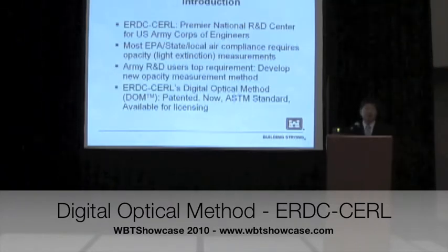EPA, as well as state agency, issued a permit to the air pollution sources or stack owners at installation. All the air permits require opacity measurements. Opacity means how opaque the plume is.